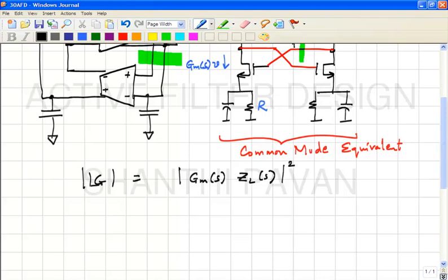The square roots. Correct? Now, if you want to ensure absolute stability, right, what do you think you would like to do with this magnitude? I mean, where are the closed loop poles sitting? The closed loop poles are the roots of 1 minus loop gain in this particular example, because the feedback is positive, that's all.